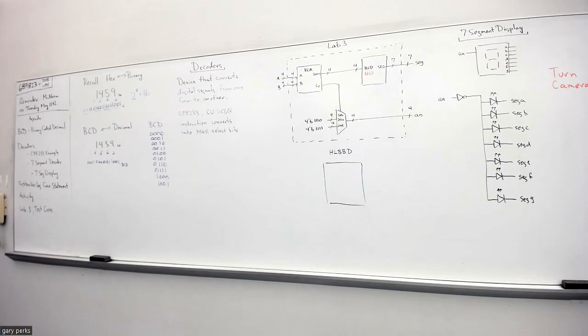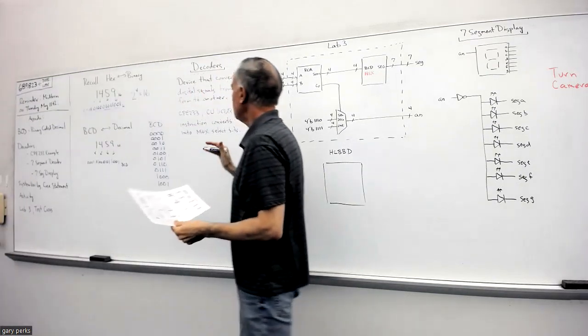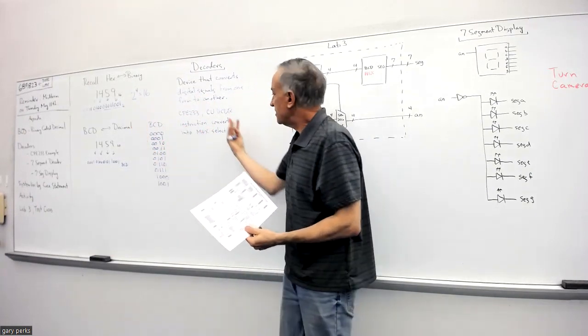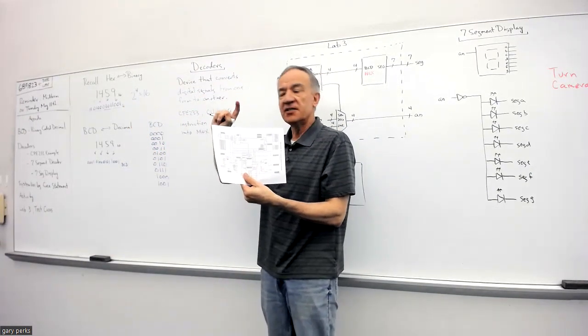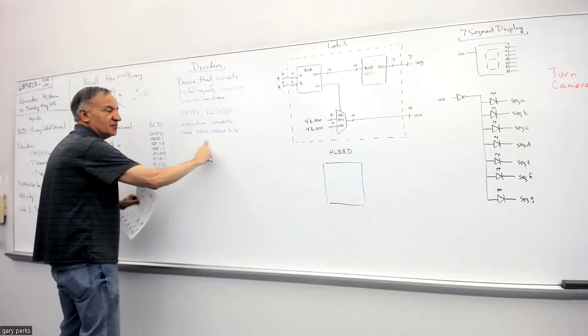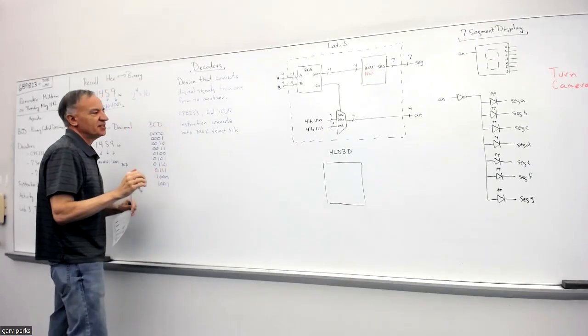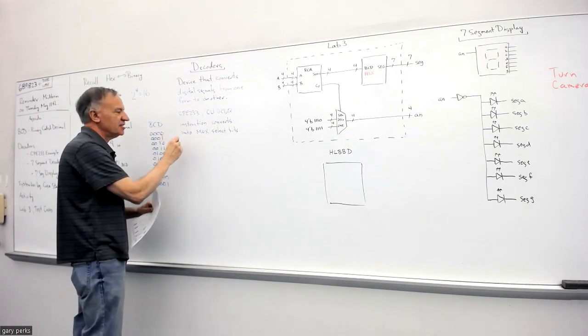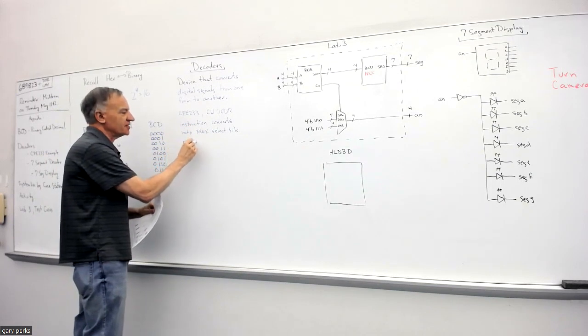The PC source is the select input to this mux over by the program counter. That's what PC stands for. And then RFWR select is a select input that goes to a mux that's by this thing called a reg file. Okay, so you see that decoder in CPE133, it's converting an instruction, which is a digital signal because it's made out of bits, and it's converting it into outputs, which are either 0 or 1. So again, into another digital signal, and by outputting these mux select bits, what's occurring is that the control unit is routing the data through the microprocessor.